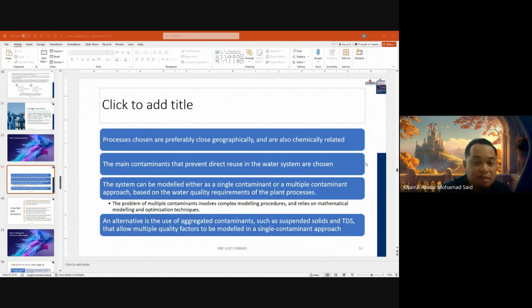For the first question, during the plant audit, the gas scrubbing unit, the water is sprayed to absorb the sulfur dioxide. Remember, water acts as a sponge from a flue gas stream. How should this operation be classified? It is a mass transfer operation. So in this case, the water is a mass separating agent.